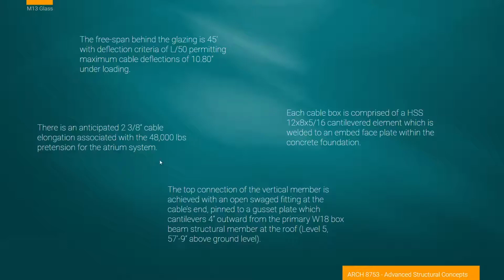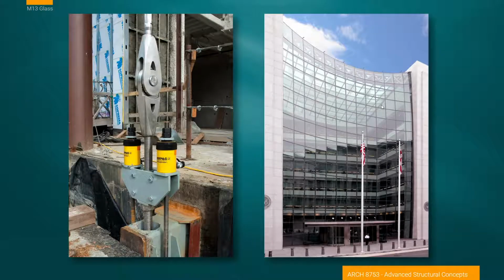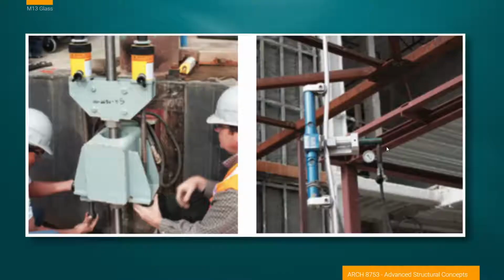I bring up all of this complexity because this looks like such a simple system, but because there is no vertical structure here, it's all cable systems. A lot of tension has to be pulled in order to hold this. I guess we could call it now a membrane, a facade, rigid enough so that it cannot break the glass and not cause leaks during deflections.